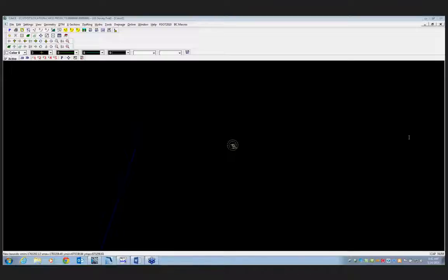It says, what is the point of having annotative line scales if you're setting your text to be false? It's a good question. What I have shown you is pretty much a transition period. Setting the text to annotate also works, but you have to be aware of where that text is. As you saw in the township range line text on the right-of-way map, justification affects it. So if it's not centered, it will move. If you have it justified left or left upper or left lower or right upper, right lower, or even middle upper and lower, that text will significantly move.